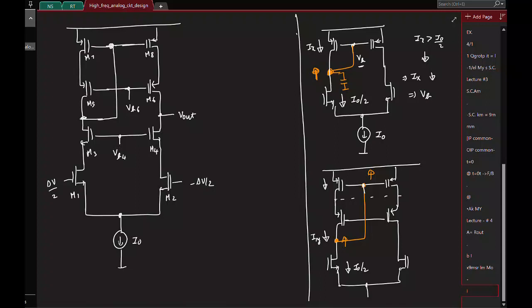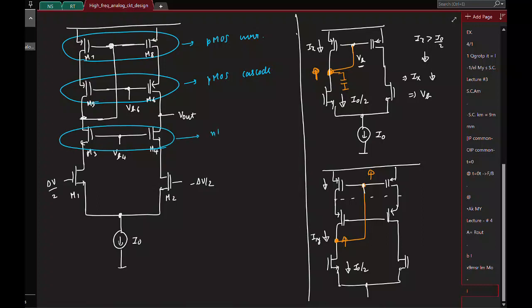Okay, so this might look very big, but if you think about it, it's pretty simple. This is basically our PMOS current source, right? The second stack we have here is the PMOS cascode, this was the NMOS cascode, and this is basically the final differential pair.